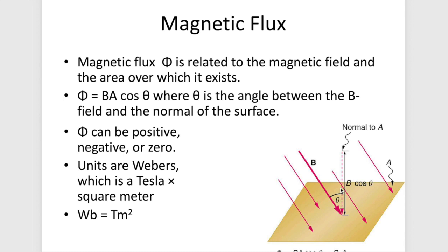When the great debate between Edison and Westinghouse and Tesla was about whether we should use AC or DC in our electricity generation in the United States, alternating current or direct current. When we were using direct current, you had to have generators really nearby. You couldn't transport that energy through lines very easily because the current would be very large, and the energy lost to the environment through heat, the wires would heat up, and we'd lose most of the energy by the time we would transport it very far at all.